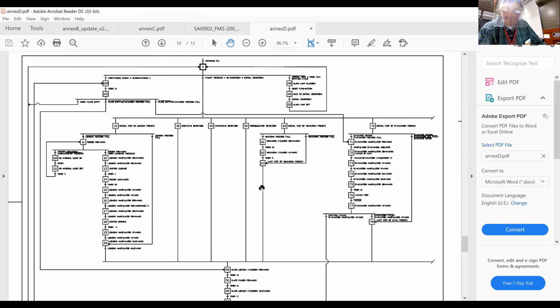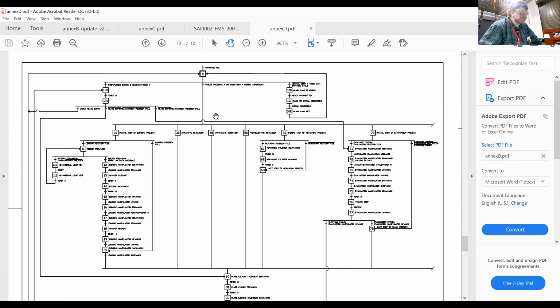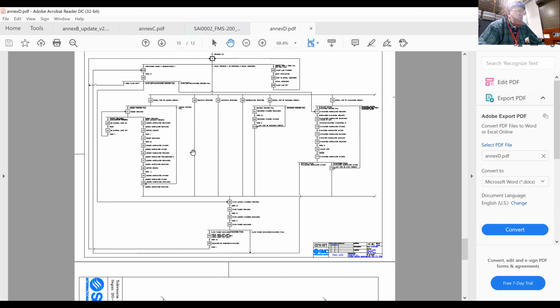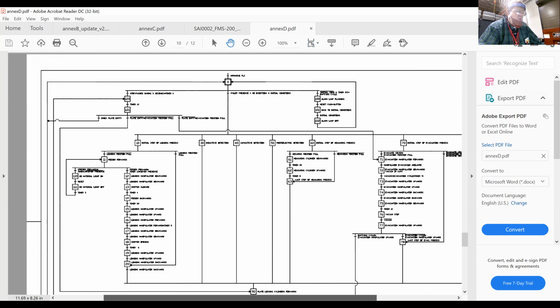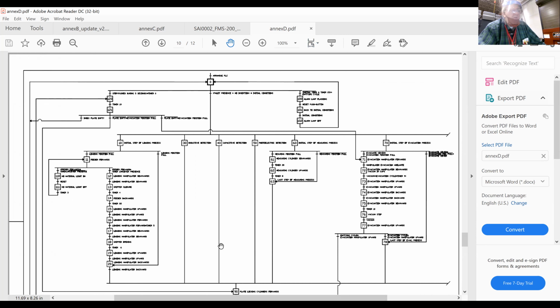Okay, so whoever's watching the video out there, the graph set is this graphical flow chart that represents the entire layout of the PLC program that runs that station. It gives you a graphic to understand the overall flow of the PLC program in steps, and those steps exactly match the steps in the PLC. So it's a really good way to help you know where to go in the program when you've got problems. Those of you that are not with us, you will get a paper copy of this whenever you come. Okay, and that's all you need to know right now.